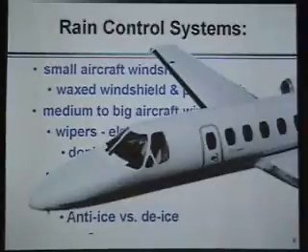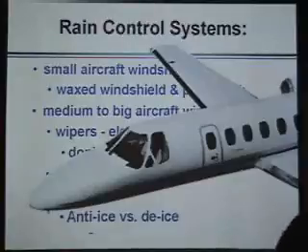However, you've got to watch out if you have a plexiglass windshield and you're doing this. I'm sure there will be a restriction for operating this on the ground. This system works well as an anti-icer to keep the ice from forming, and it'll de-ice because it's hot enough. Of course, as you're flying along, the air is nice and cold, so you won't have to worry in flight about melting your plexiglass windshield.